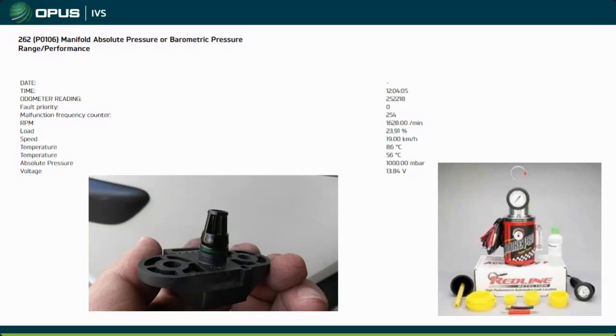So the only other thing that I wanted to talk about is just parts in general. These crankcase breather valves in the 3 liters and the 2 liters especially are very well-known issues around the world. Every engine is going to have some issue with them. And the aftermarket is sort of taking note of that, and a lot of them are starting to produce aftermarket valves.